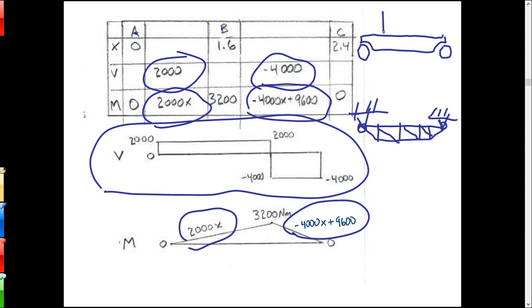When you start loading this thing up with whatever you're carrying on it, the moment magnitude is going to be quite low at the ends, which is where the wheels are at. So you could probably get away with carving that beam back at the wheels because there's not that much of a moment, which is quite convenient because you can fit the wheels in there, see? So that's why this visual information can be very helpful when you're looking at it.